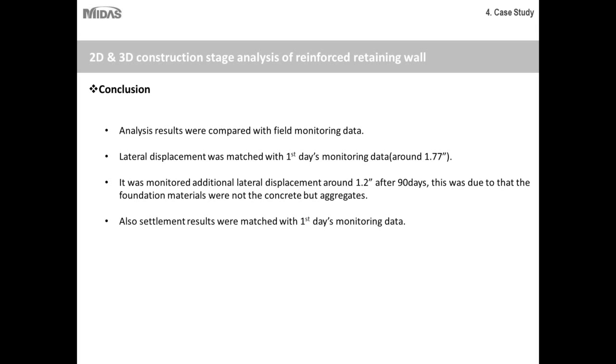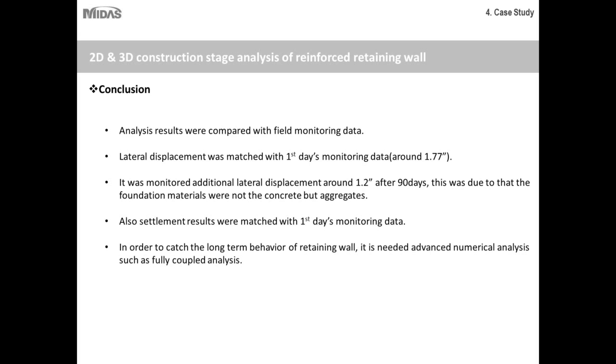So the settlement results became very important, and they had to first monitor the settlement that was going on in the field and compare it with what they were getting from the model file, and they were able to get a perfect match for the first day monitoring data. So like I said, in order to catch the long-term effects of the retaining wall, it was needed to do advanced numerical analysis such as fully coupled analysis. So that led to an advanced set of analysis that needs to be performed, which is not commonly done when you are dealing with very conventional, simple, straightforward retaining walls.